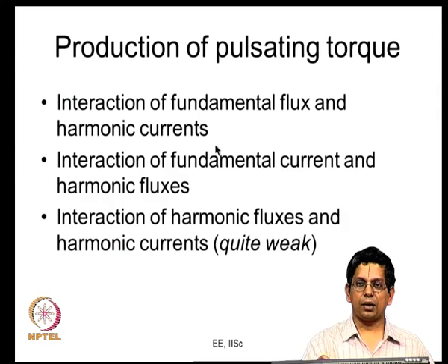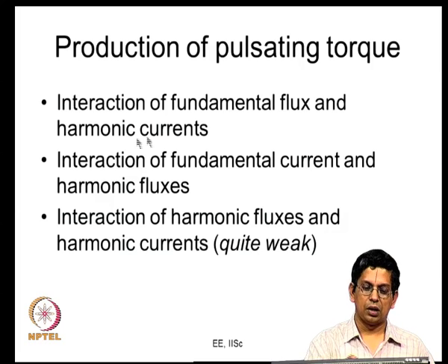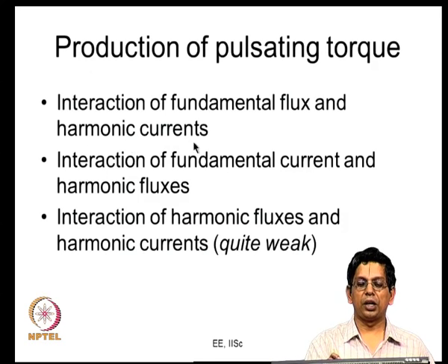So, let us say we look at the stator's fundamental magnetic field. We can look at the fundamental flux of the stator, and if you want to look at a harmonic magnetic field produced by one of the rotor harmonic currents, then you can look at the harmonic currents. So, to consider an interaction between the fundamental magnetic field produced by the stator and one harmonic magnetic field produced by the rotor, I can consider fundamental flux corresponding to the stator and a particular harmonic current corresponding to the rotor. So, I can look at this as an interaction between these two.